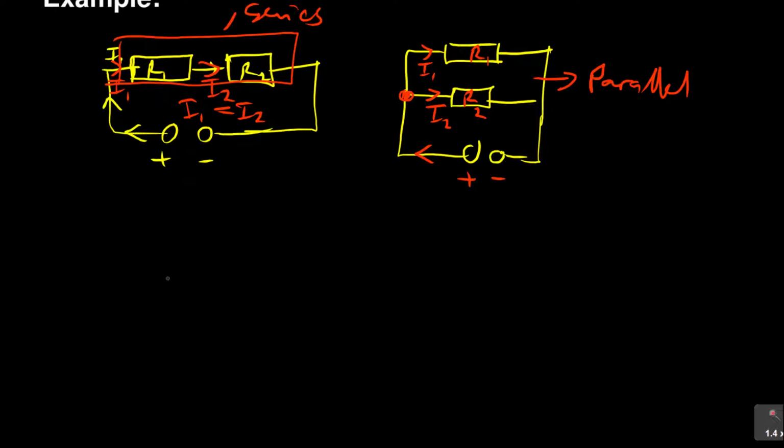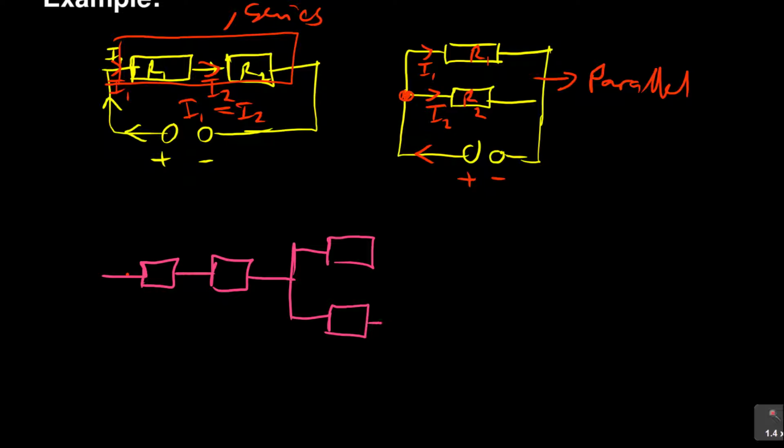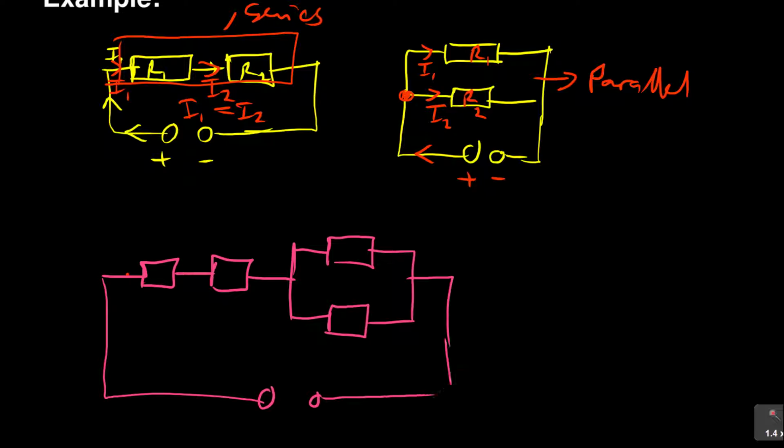Now when we are looking at this scenario where we say it's a series and parallel circuit, we are saying you can find resistors like this, which are in series and connected in the same way. If you look at this diagram and follow the flow of current here, you can see that R1 is in series with R2. The reason being is the same current is passing through. If it's I1 here and I2 here, we are saying I1 is equal to I2.